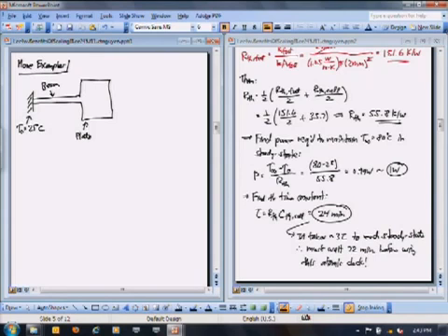And so how are we going to supply heat to this? Well, one way you could supply heat, right? You could put a heater on this, but let's take a different case. Let's say we take a laser and we nail this thing with a laser beam. Okay? So that laser is now going, it's not going through this thing, it's being absorbed by the structure. So we'll assume that the properties are such that it absorbs the energy from the laser, and all of it. Right? How are you going to model this thing? So what's the equivalent circuit going to be for this, so that you can determine, okay, for given laser power, what's the temperature going to be on this thing? So how do we want to go about modeling this thing? In other words, what's the equivalent circuit?